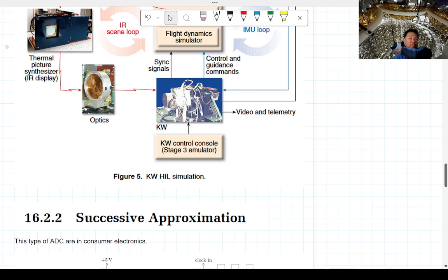A lot of physics experiments use this. For example, in the experiment on the neutrino detector, we sample every 2 nanoseconds, right? And anything other than flash ADC will be too slow to do that, because unfortunately the speed of light is finite. For the information to travel through a couple of feet of signal wires, that already takes 2 nanoseconds. So that's usually almost the very best speed.